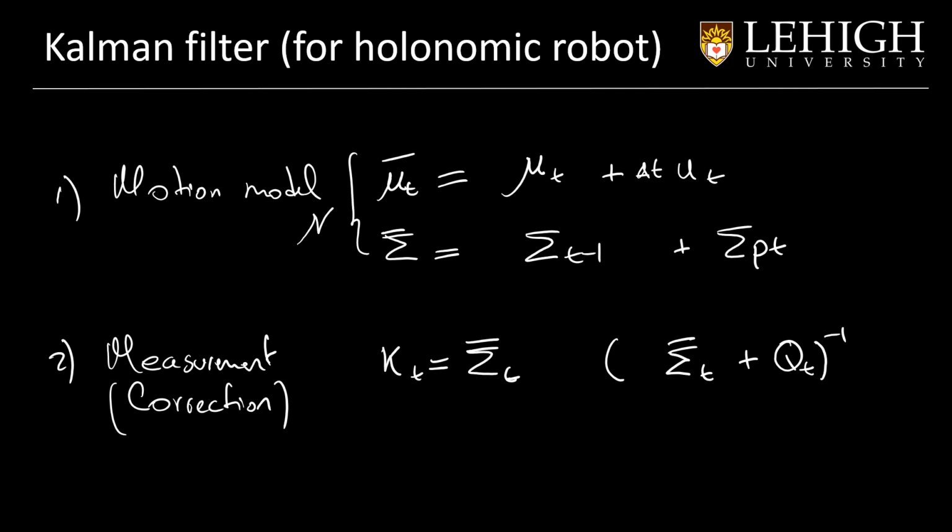Every time we try to identify the location using a sensor, we will have an associated error, and we abstract that with the covariance matrix that is here. And we will use this Kalman gain to obtain the normal distribution that represents the location of the robot.